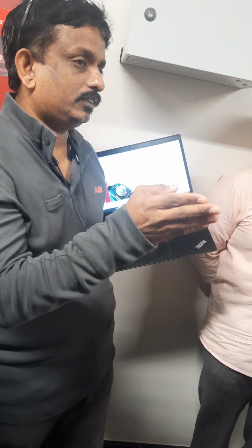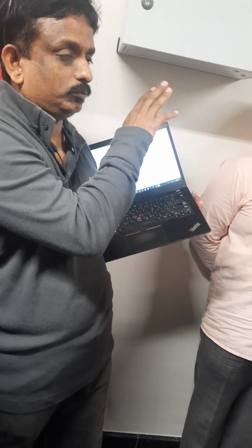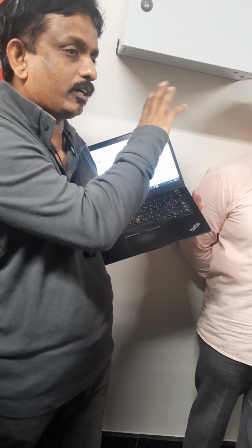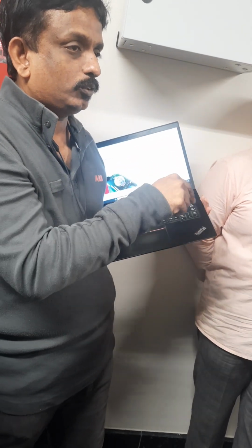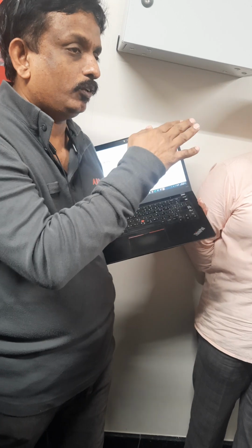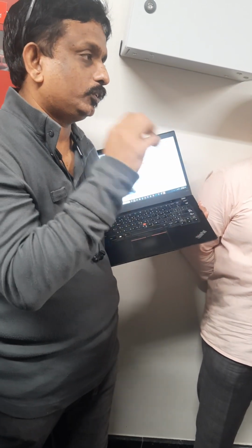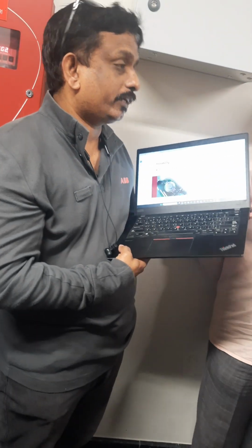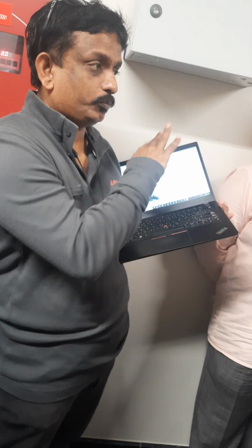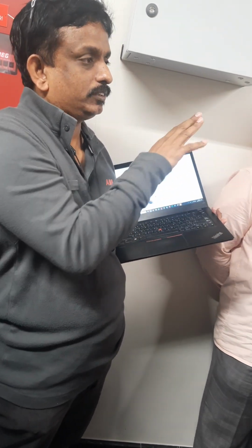Another thing you need to always make sure of is the battery backup for the breakers, because the breaker will work depending on the supply. If the supply is lost, the drive cannot operate the breaker. So you need to check the UPS supply for the breaker. I just explained the safety; that always needs to be available.